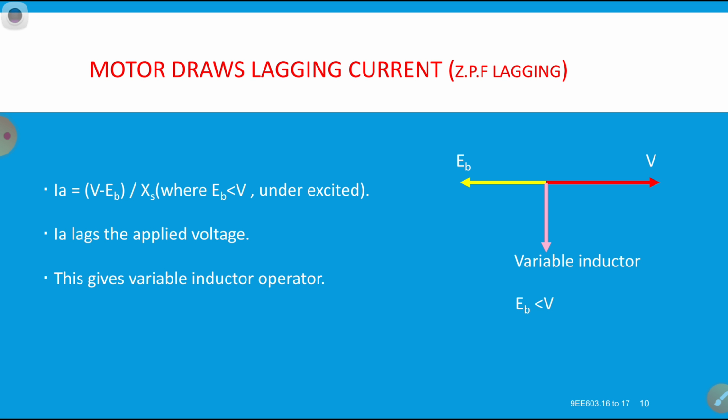At that condition, we are going to add some inductive load on the system. In our substations, reactors are also readily available. By connecting the reactors, whatever excess reactive power is in the system is consumed by these reactors. So the voltage automatically comes to the normal value.